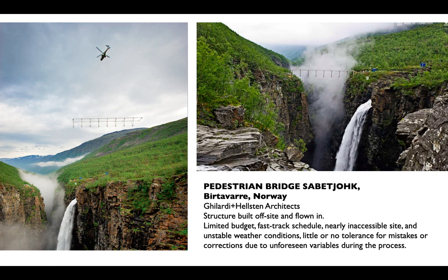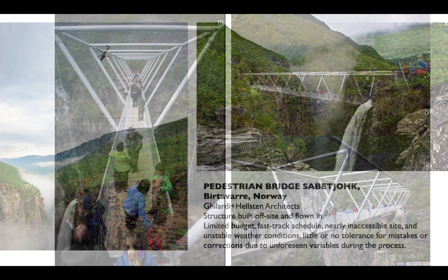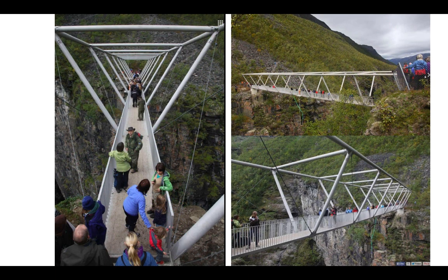So they have this kind of 20-minute window that they can get the bridge flown in, put in place, and then a very, very small team of construction engineers on site actually attaches it to the foundations. Now, a couple of things to point out, right? One is that this takes the need for lightness to an extreme. Not only are we worried about the dead load of the bridge when it's in place, but obviously the engineers here have to worry about how much a helicopter can actually carry.